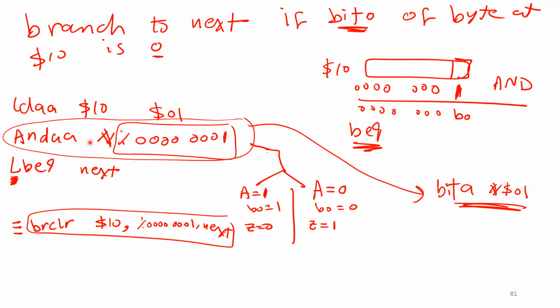So this instruction, actually, guys, number 1 is going to do logic AND. Number 2, update the flags. Number 3, store the result in A, right? If it is okay for you to destroy A, then that's okay. Otherwise, we have another instruction.